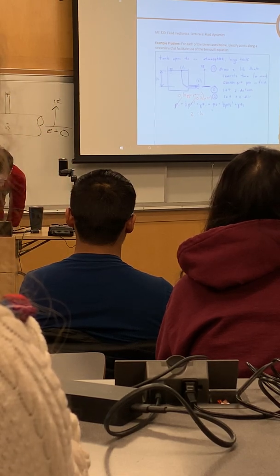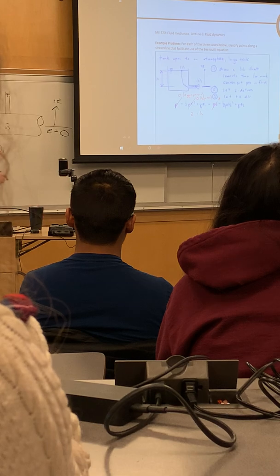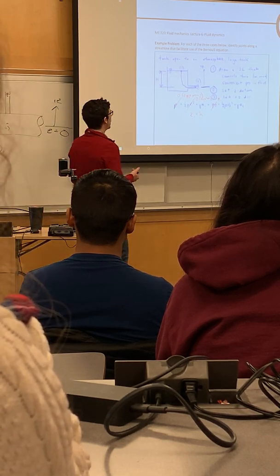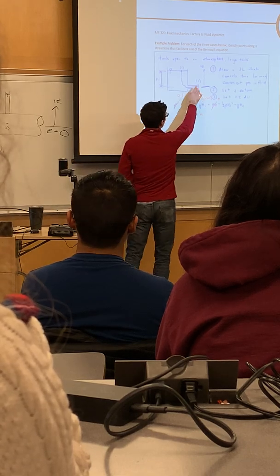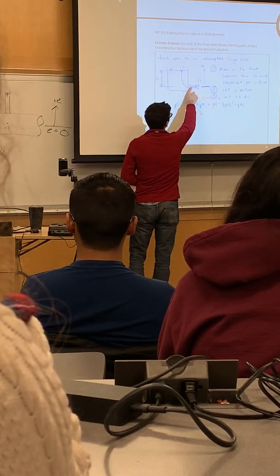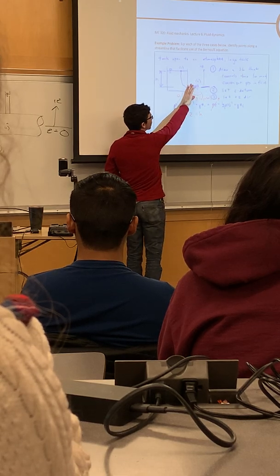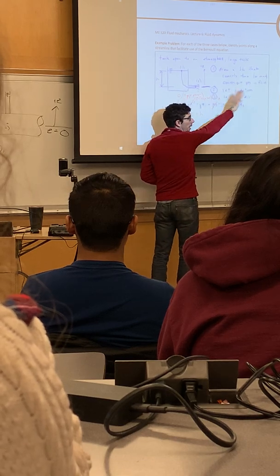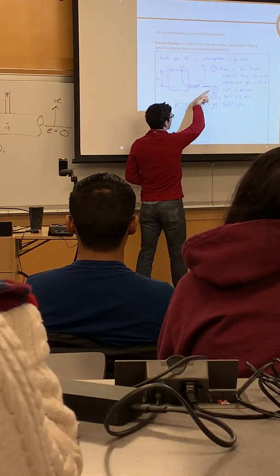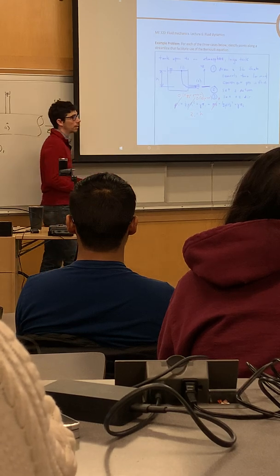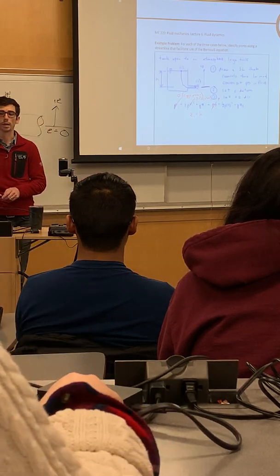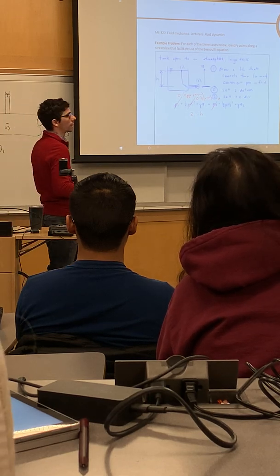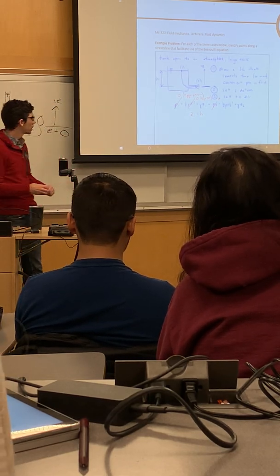Otherwise, would we have to have like something there to measure pressure? Yeah, exactly. Or you might be given it, or you might be asked to solve for it. We have an example of this in the next lecture. But imagine we were to push point 2 back up here, or you were to not be told that this pipe has an opening, and you're just told to solve for the pressure somewhere in that pipe. Then we can't neglect the static pressure at point 2. I think we can do an example like that in the next set of lecture slides.